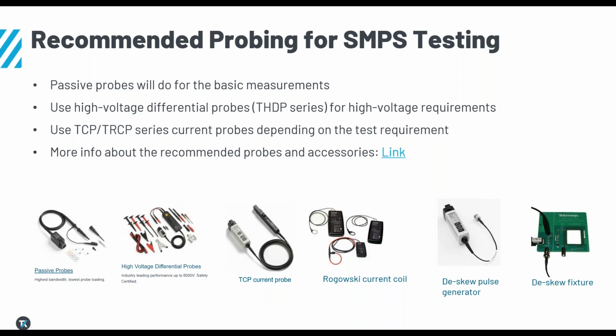And Satish also did mention the importance of deskew. If you're measuring power, you have to understand that's voltage times current. And when you have slight skew within those measurements, and every oscilloscope, every signal path is going to have some skew. A lot of that's accommodated when you plug in the probe, but you want to make sure that that deskew is taken care of.